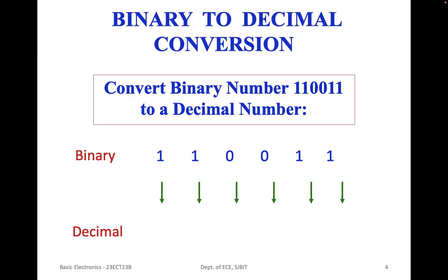Code conversion is basically the process of changing a code with a specific bit structure to another code with the same or a different number of bits per character interval. In digital electronics, a code converter is a logic circuit that takes bit patterns representing numbers or characters in one code and outputs the corresponding representation in a different code.